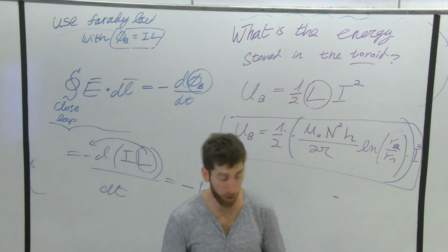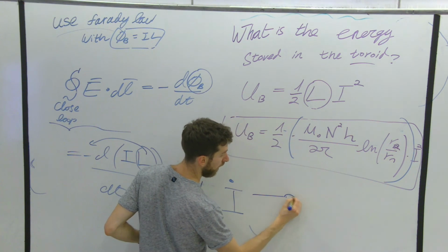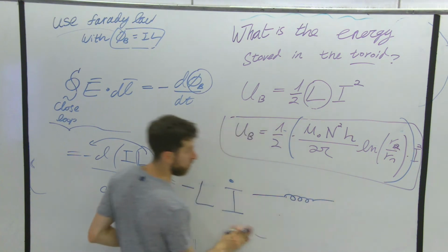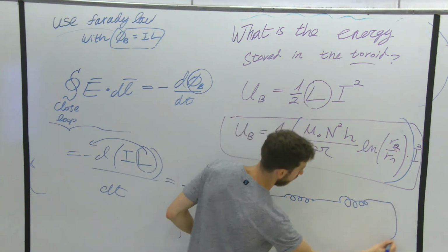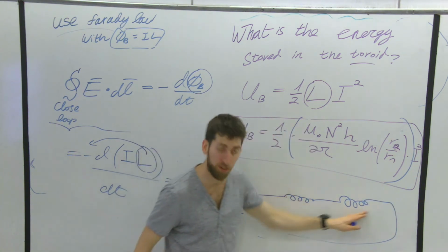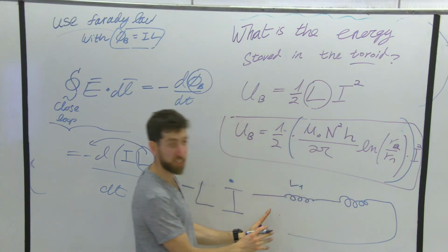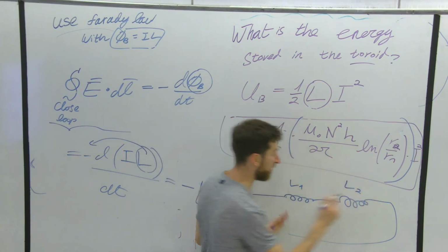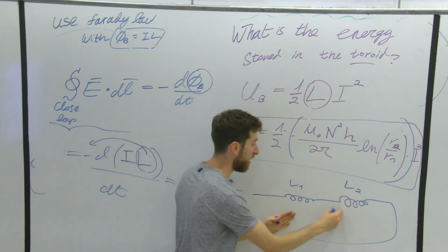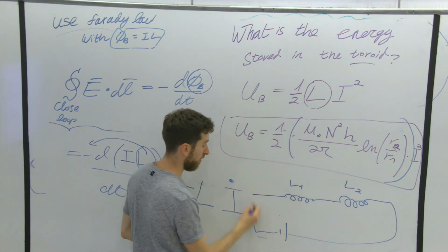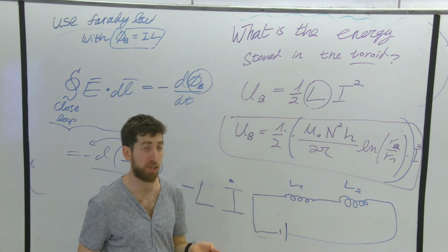And also you can connect others. For example, if I had here some toroid, and this toroid is connected to another crazy-shaped device, I know that in general this one has some inductance, and this one has some inductance. I don't need to solve everything from the beginning. I can understand they are connected in series to each other. So inductors actually sum up like resistors.